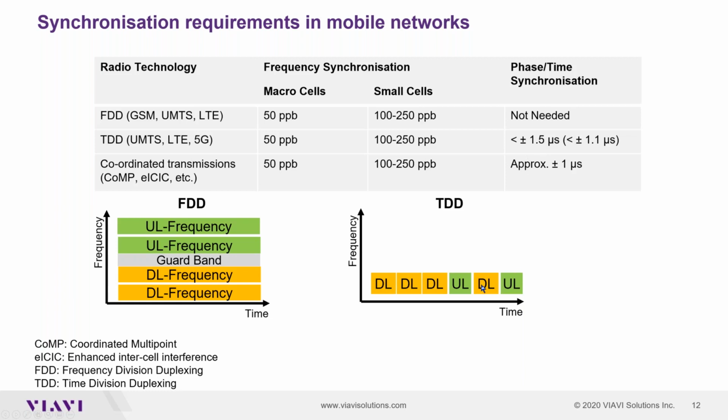You see on that picture here, it's not only one frequency from the cell side to the mobile, and within that frequency we have a downstream and an upstream direction. So it's organized, it's called a 5G frame, and it's organized in slots for up and for downstream. So you switch in between the direction. If there is a second mobile, it has the same frame structure. It has at the same time down and upstream, so no problem.